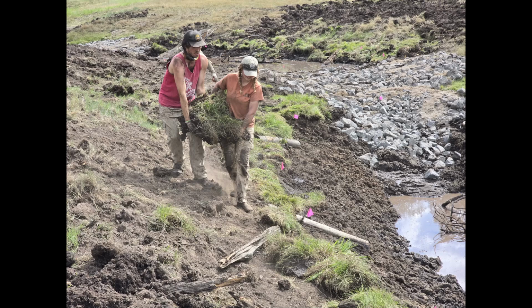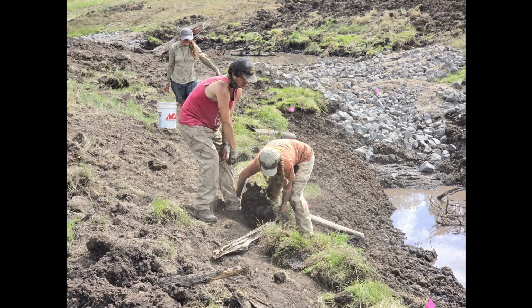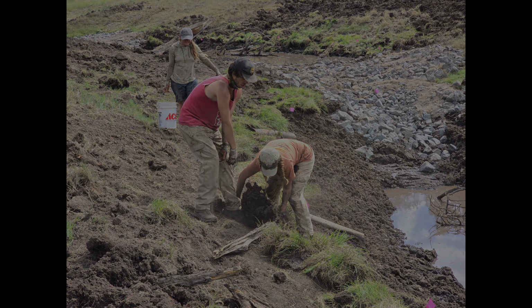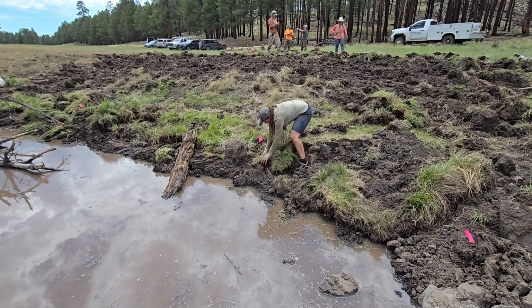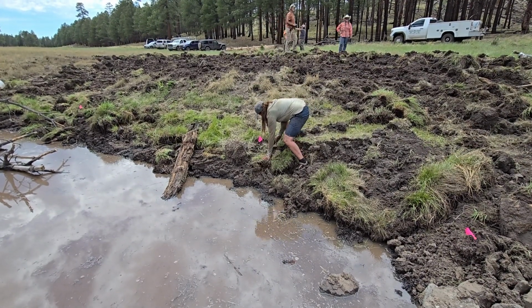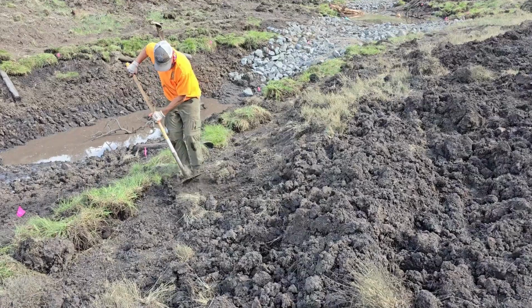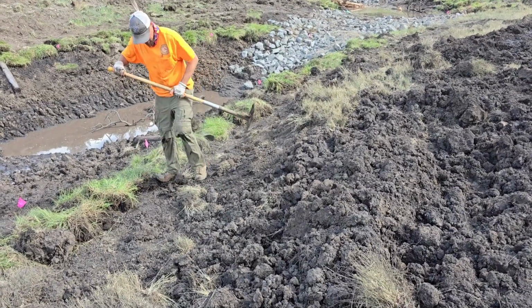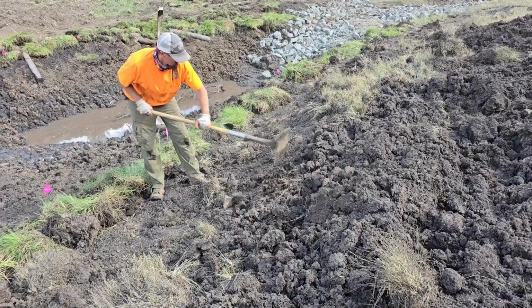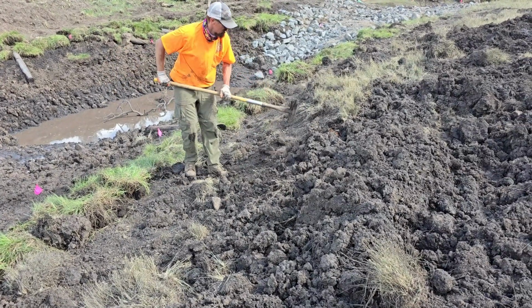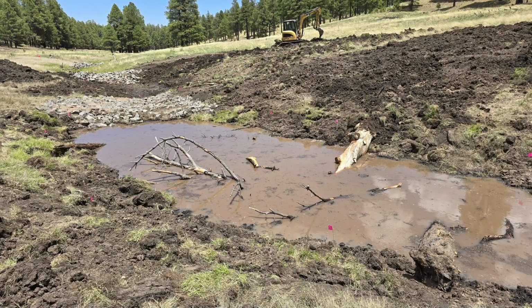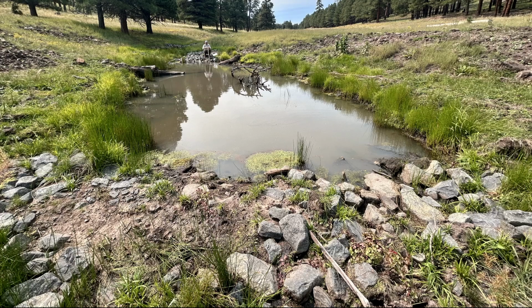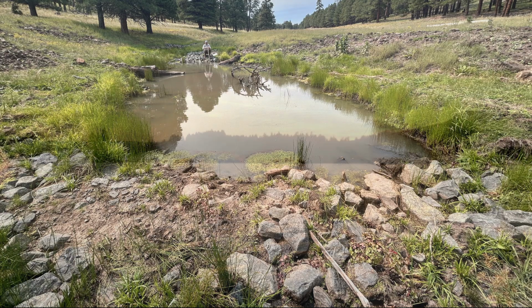The smaller clumps of sedge were planted by hand along the water's edge in the restored wetland. I used the laser level to take an elevation reading at the entrance to the spillway. I then used the laser level and the survey rod to place wire flags at the planned water level in the restored wetland to serve as a guide for planting. Soil was raked by hand to cover the roots of the sedges so they would grow. Marks left by the excavator bucket and the excavator tracks were also raked out by hand. Within 1 day of construction, the restored wetland had filled with water. Here's how the wetland appears 3 months after construction.